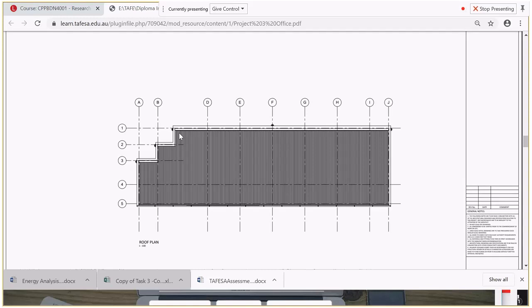So lines like that, but leave 600 mil here, here, here, here, etc. around to be able to access the edge of those banks of solar panels. So the solar panels can be butted up to each other in long lines, but with a bit of space around the outside of those lines, 600 mil for servicing those solar panels.